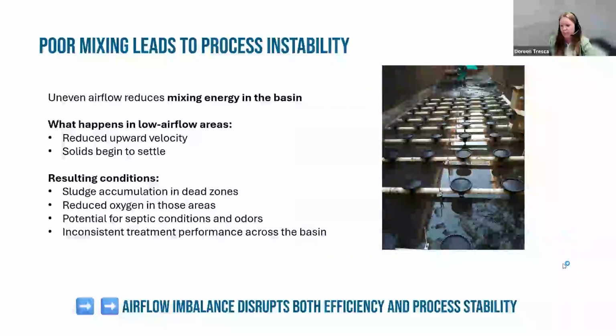Over time, what does that mean? You're going to start having sludge accumulating in low energy areas like corners, between the grids, along the walls. As sludge builds up, these areas can lose oxygen and potentially go septic, leading to odors and other much bigger process issues. Over time, the other parts of the basin may be over aerated, which wastes energy,